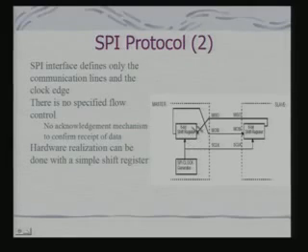So, it will generate the clock, and depending on the data which is getting generated, if the slave is generating the data, it is shifted out by the clock, and the data is coming here. This shift register is also effectively clocked by the same clock, and so the data would be ready. In fact, this is a very straightforward way. If I continue to use it indefinitely, then the same data will go from master to slave and from slave back to master.